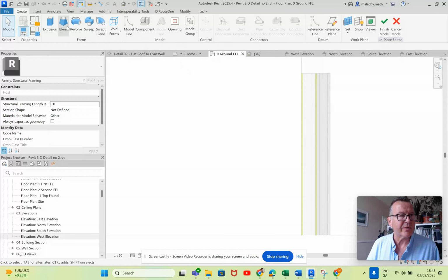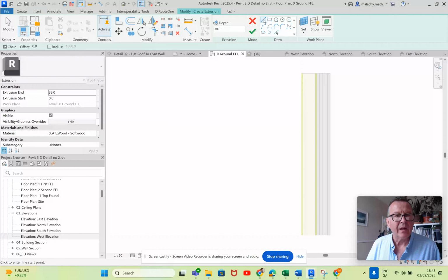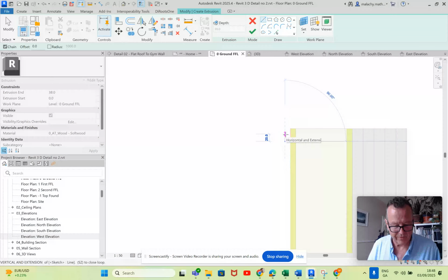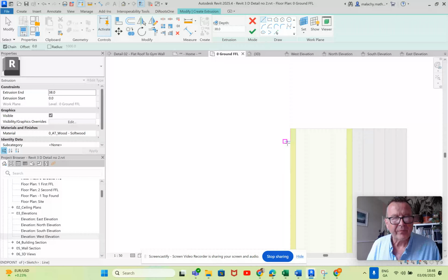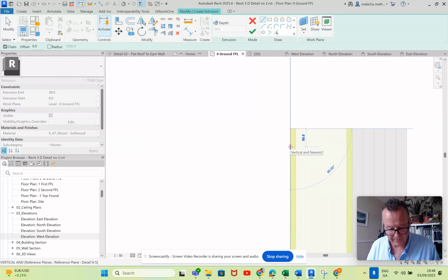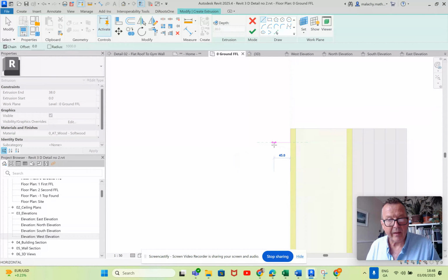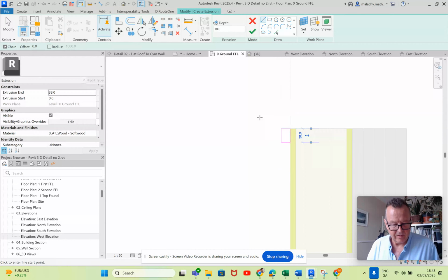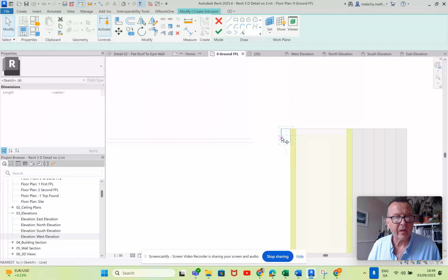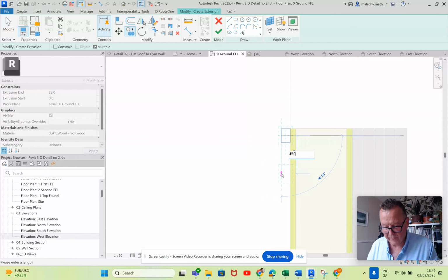Okay, now we'll do extrusions here, and let's draw the first one out. So it will be, I said 30 by 38, didn't I? Okay, let's just delete that. Right, do this properly. So 38, and this way 25. Okay, back up 38, 25. Now escape, I can select those and I can copy them. So from there, and we'll put these at say 450 centers.